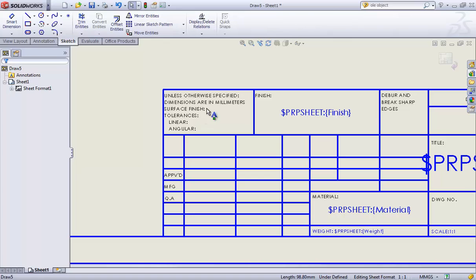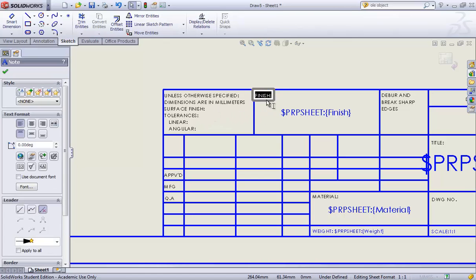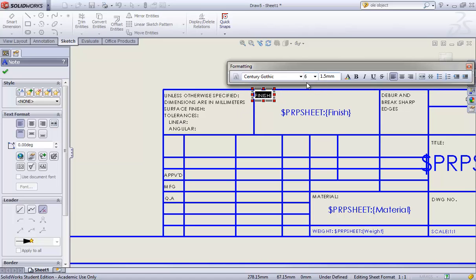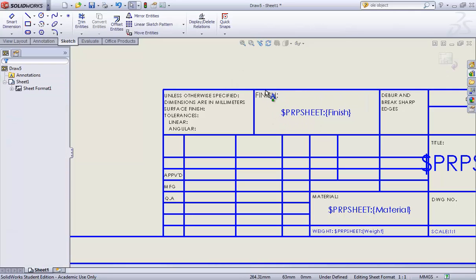if I wanted, I can change this text by double clicking that, which will take me into the edit mode. This is where I change the font size. Generally, font size of 2mm or over is better. It's more ergonomic than something small, really. So I tend to go to font size 8 at least, which gives me the correct one roughly.